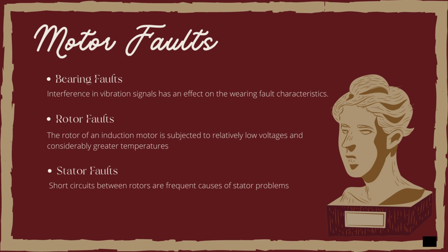The primary cause of stator failure is insulation degradation, which will result in turn-to-turn short circuits. Extremely high currents flowing through the shorted turn allow destruction to spread when a short circuit in a turn develops.